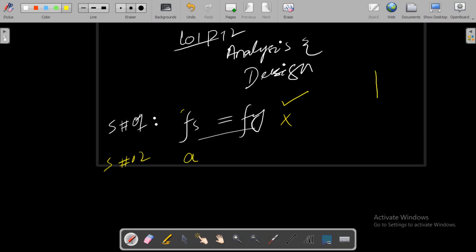Let's say this is my equivalent rectangular stress block, which is C, the compression force, and the extreme fiber compression is 0.85 fc prime, and the depth of this block is denoted by a. I have explained this in a previous part, and this is a divided by 2.